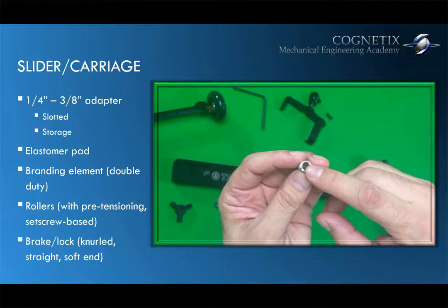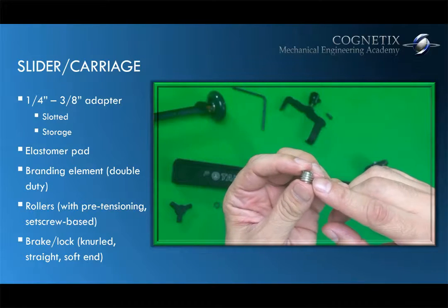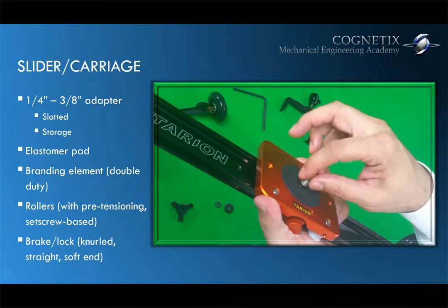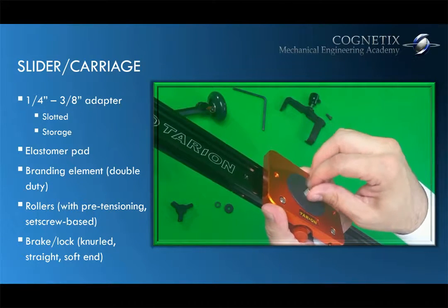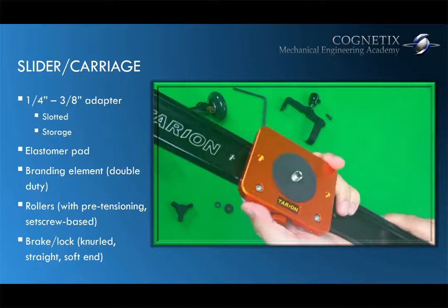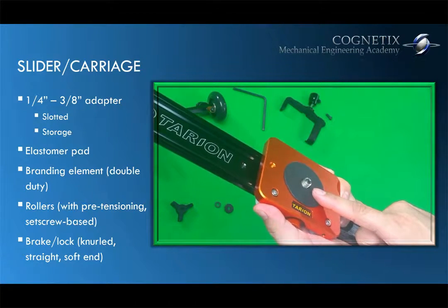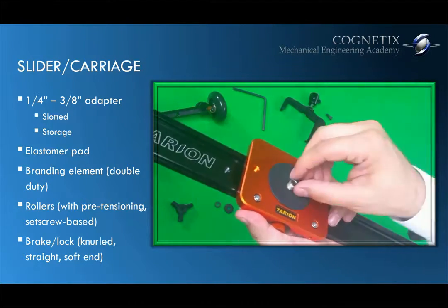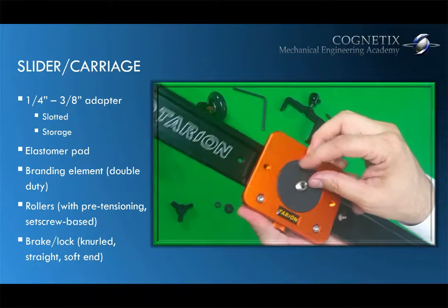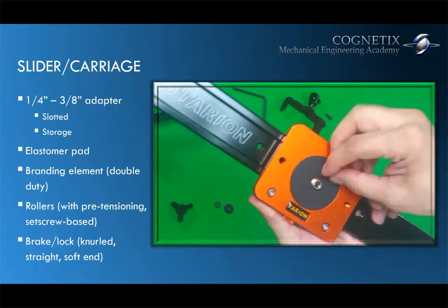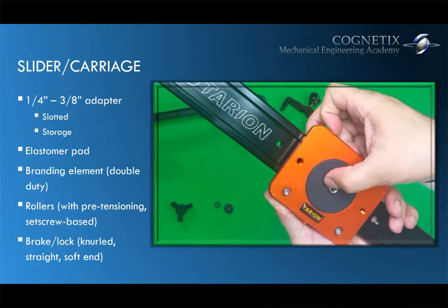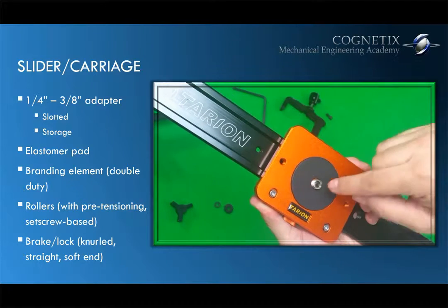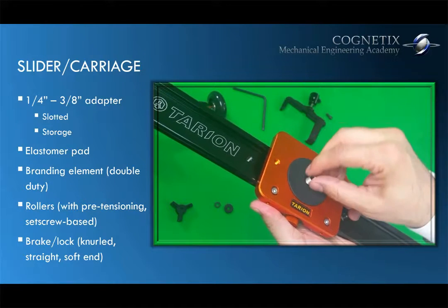Internally, it's a 1/4-inch thread. Externally, 3/8-inch. So the way it works is, very simply, you thread this onto the existing fixed 1/4-inch thread until it bottoms out. And now you're left with a 3/8-inch connection for your other accessories, okay? Very clever, very simple, not very costly, and the end users will really appreciate this. Now, I just threaded it by hand, but you can see that they have a slotted connection there, a slotted slit for screws. A slotted screwdriver could tighten this as well. Okay, I'm going to go ahead and remove this.